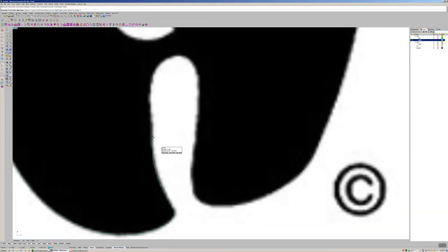Now again, like I mentioned to you, shortcuts are the name of the game. One of the greatest shortcuts is this: once I use a command, we end the command by right click. So I get here, I'm going to end it right now. Right click. I just ended the command.